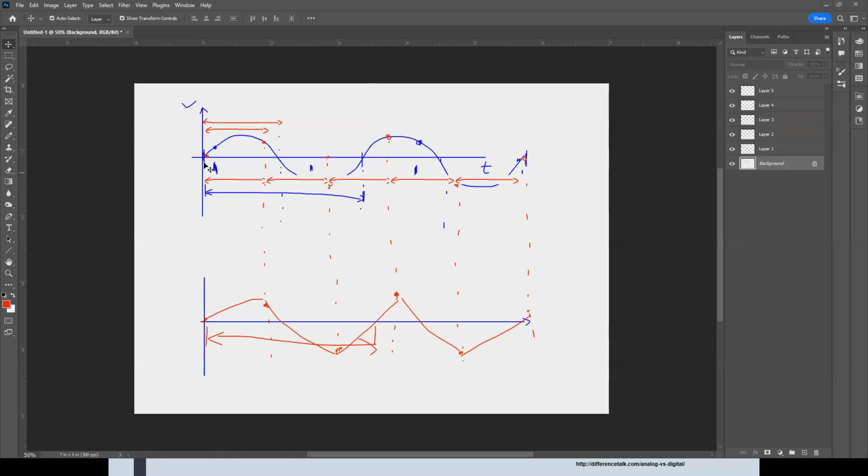If we started sampling right at 0, then if it was exactly half, we would just have all the 0 points, so we would end up with a straight line. So it's a very rare situation. You will never hit that point. However, it is a possibility that something like that can happen. So always try to have less than half. Then you're not going to end up with all the zeros. So at least you're going to be able to recreate the frequency.